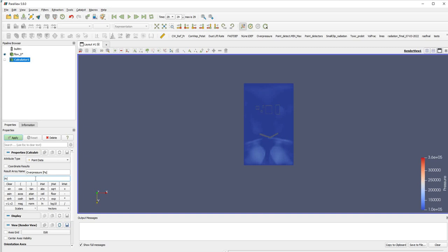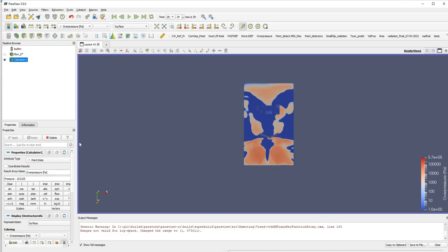And you just go pressure, which is a parameter that is already in there. You could select it from scalars, by the way, if you're worried about spelling and so on, minus the atmospheric pressure, which is this 101,325. And it calculates it. And now it's displaying overpressure,